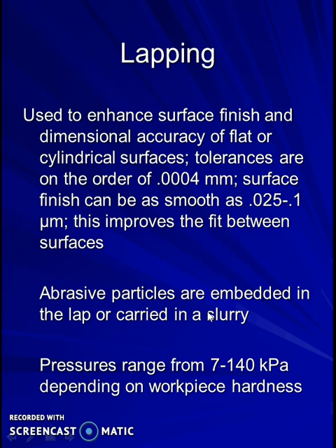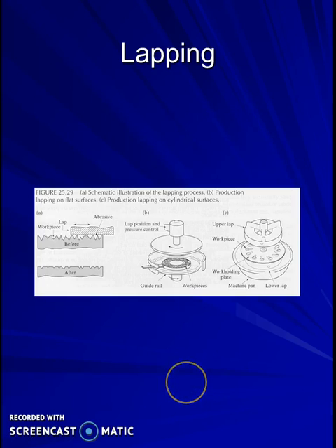Sometimes we will put it in a slurry also. Next, pressures range from 7 to 140 kilopascal depending on workpiece hardness. Whatever the pressure, based on the hardness of the workpiece, we will fix these pressures.